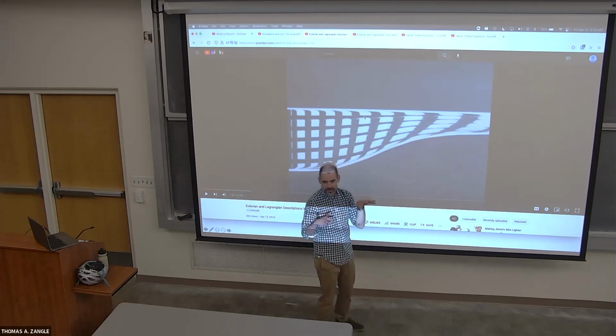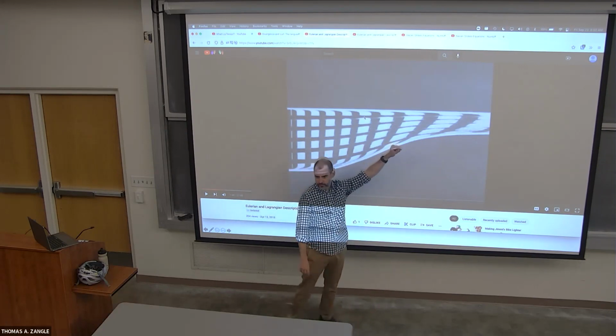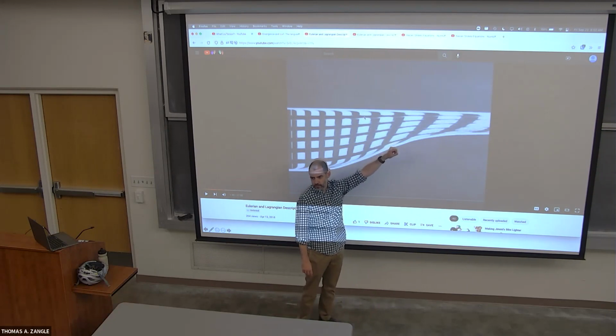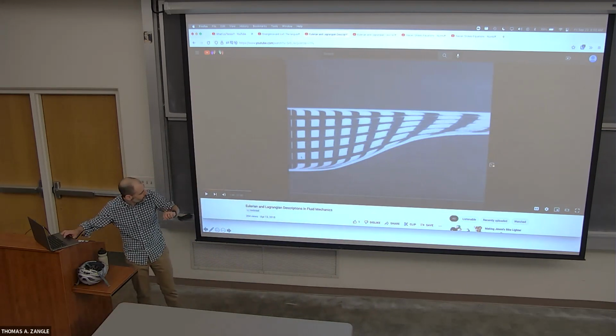So we know, steady state in the Eulerian frame of reference, if we're watching this, the velocity field is the same over time. Individual fluid particles exhibit an acceleration. Right, so that's the convective derivative term of the total derivative. And so I just want you to watch for that as you go back a few seconds. So you can see that.